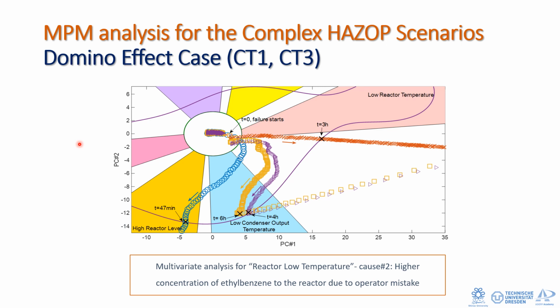Finally, the effect of solvent flow rate on the polymerization is scrutinized in this slide. The main consequence of higher solvent flow rate to the reactor with no control system in place is level increase leading to overflow if it is not controlled in time. The first protection layer, level controller LIC110, is activated, which reduces the styrene monomer feed flow rate to keep the reactor level constant.